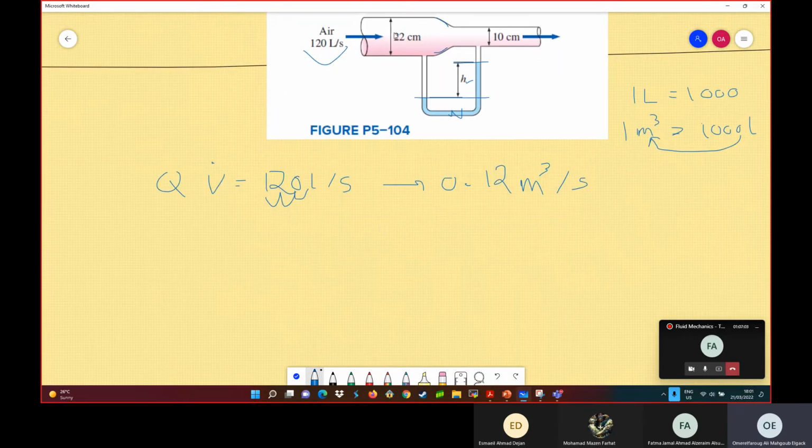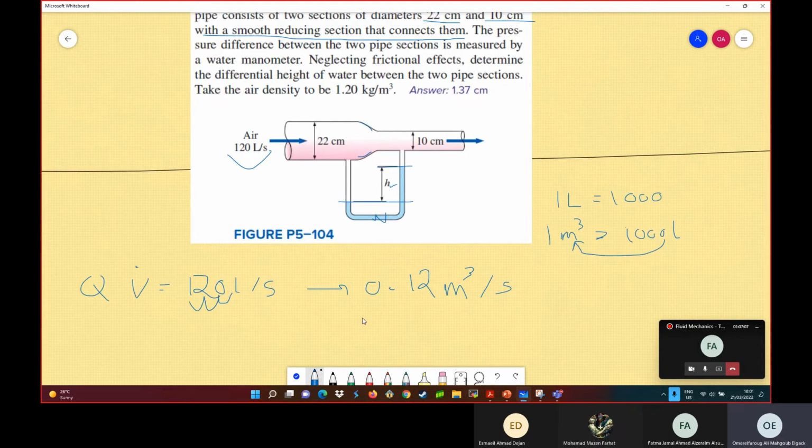And you have this cross-sectional area. For example, let's consider the worst case scenario. Where is the higher velocity, at 1 or 2? Of course at 2, because you have lower cross-sectional area, then you have a higher velocity. So we will check the Mach number at this point.